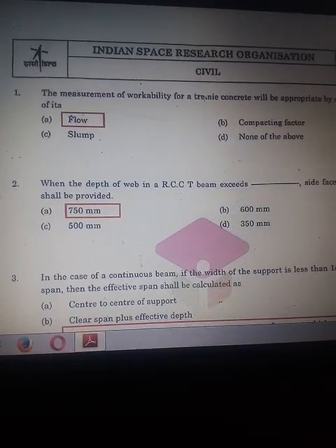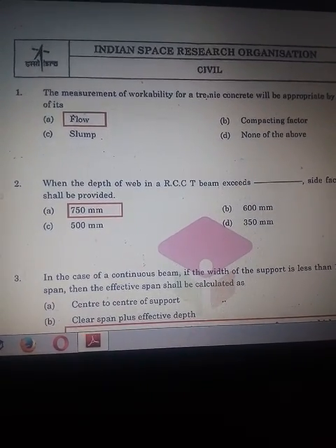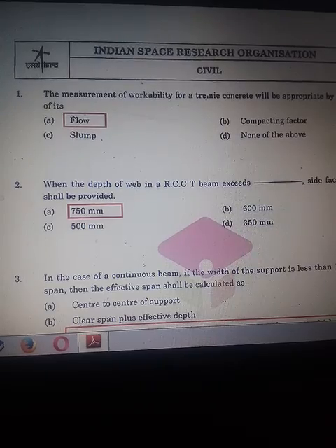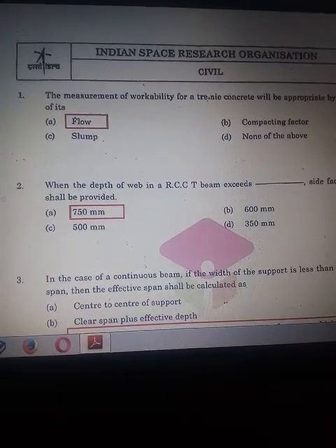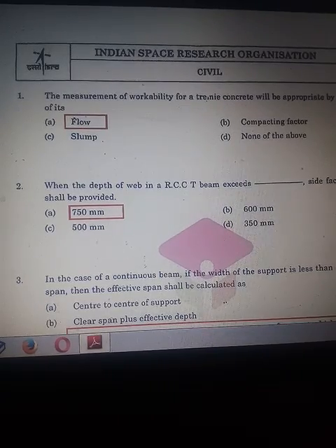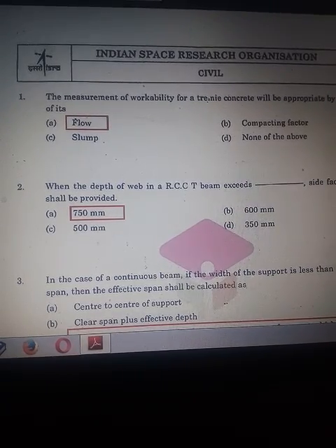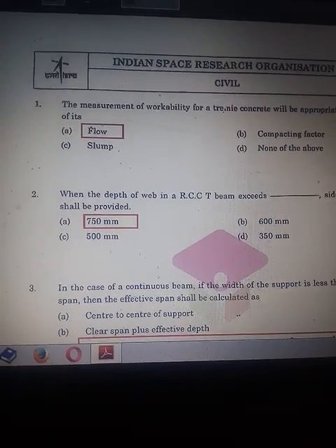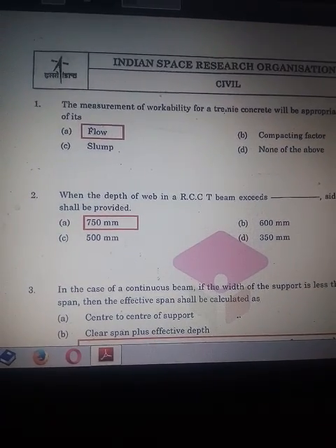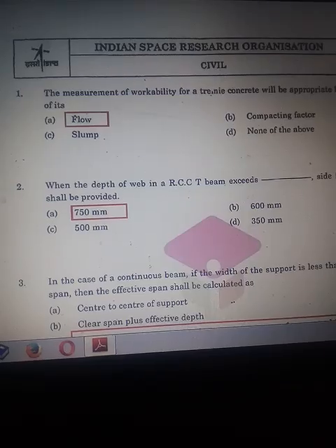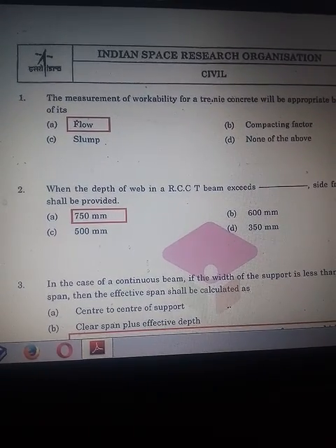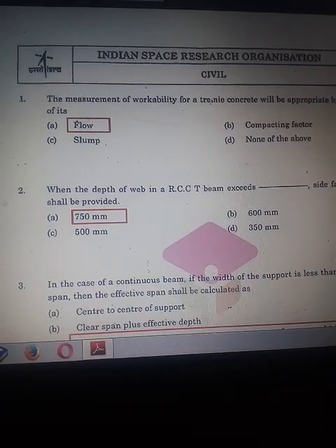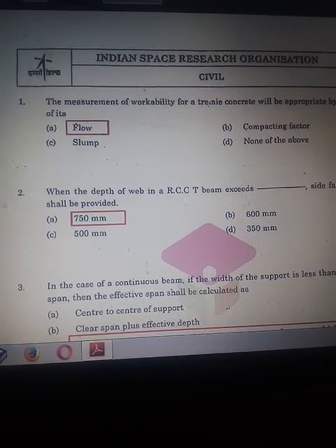Now next question, when the depth of web of an RCC beam exceeds dash, side face reinforcement shall be provided. So when the depth of the web in an RCC beam exceeds 750 mm, we provide side face reinforcement in that case, and the quantity of the side face reinforcement will be 1% of the web area. Okay,